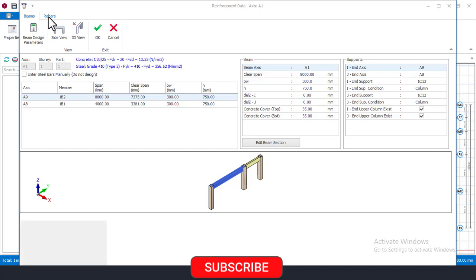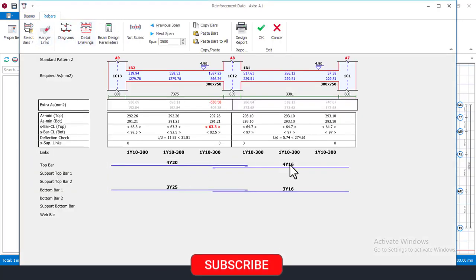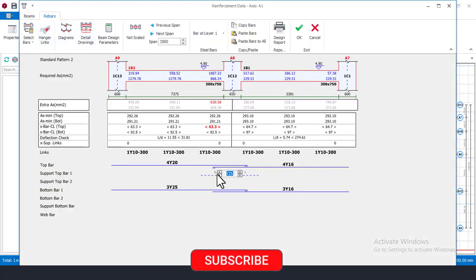So I'll just go to my rebars just now and try to use my bar to carry the weight there, and then reduce it to Y16 and try to add a bar right now. And once I add a bar, let me see, and then come here and make it layer 2. Okay, assign layer 2 because that's a supporting bar. And you can see that everything now looks okay here. I can choose to make this Y20 also and then reduce to 3 numbers. Okay, that's fine. Let me see if it still can work. No, 2 is failing here, so 3 can work.